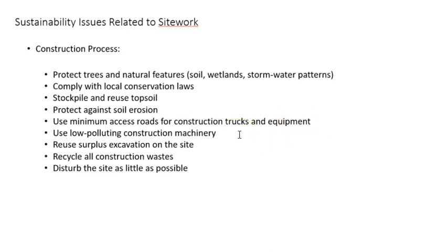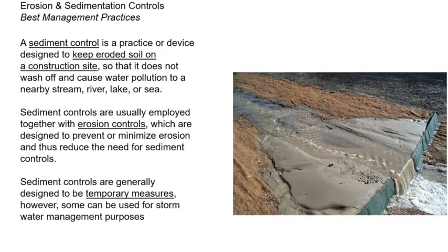How much pollution your machinery is causing, reusing the surplus excavation, what's its next life going to be, how to get rid of waste, can it be recycled, and as I said, disturbing the site as little as possible. So these are all kind of sustainability issues that a contractor would be concerned with. And now I want to specifically talk about the erosion and sedimentation measures.